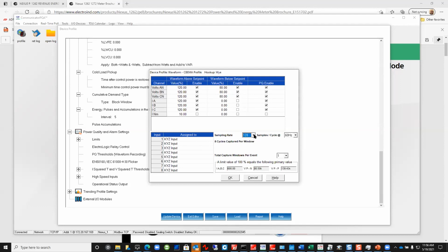But again, it all depends on what's important to you, and it does have a high sampling rate of 512. So if you want to sample for a short time, 512 might work really well for you. Over a period of time, if you really don't want to lose any event, the rate is not as good as 512, but you can capture the pre and post trigger information.